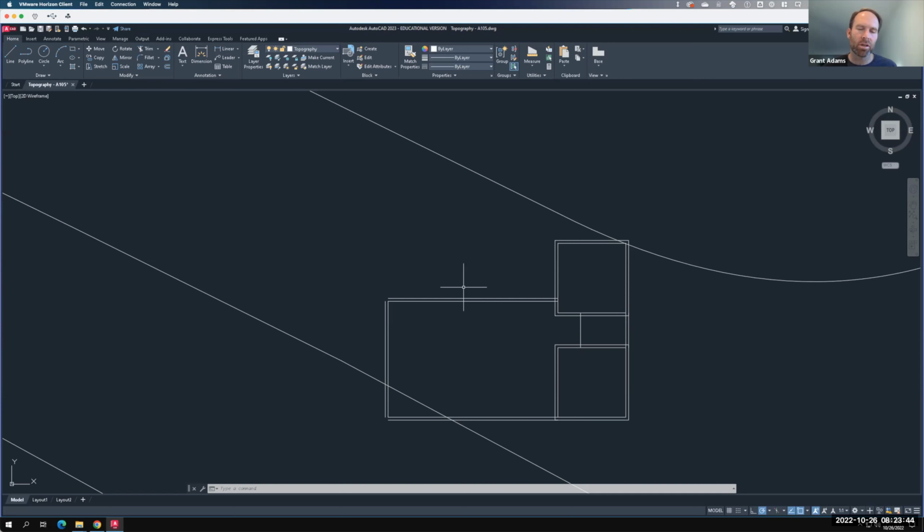When you start to fine tune a project, you want to understand what that wall makeup really is, because a wall typically, even if it's made with a 2x6, that would be 5.5 inches, but you've got a 1/2 inch of interior sheetrock, so that would get you to 6 inches. You've got a 1/2 inch of shear structural on the outside, that should get you to 6.5 minimum, but then you might have siding.